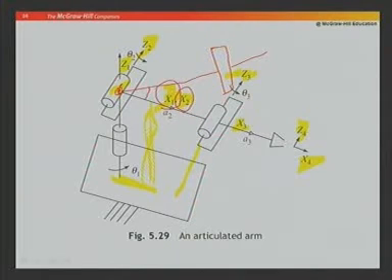Alpha 1 is the angle between Z1 and Z2, measured positively about x2. So, now Z1 to Z2 is this angle and this is positive about this axis, which is negative of x2. So, alpha 1 will come out to be minus 90 degrees or minus pi by 2, as I have noted down in the table.